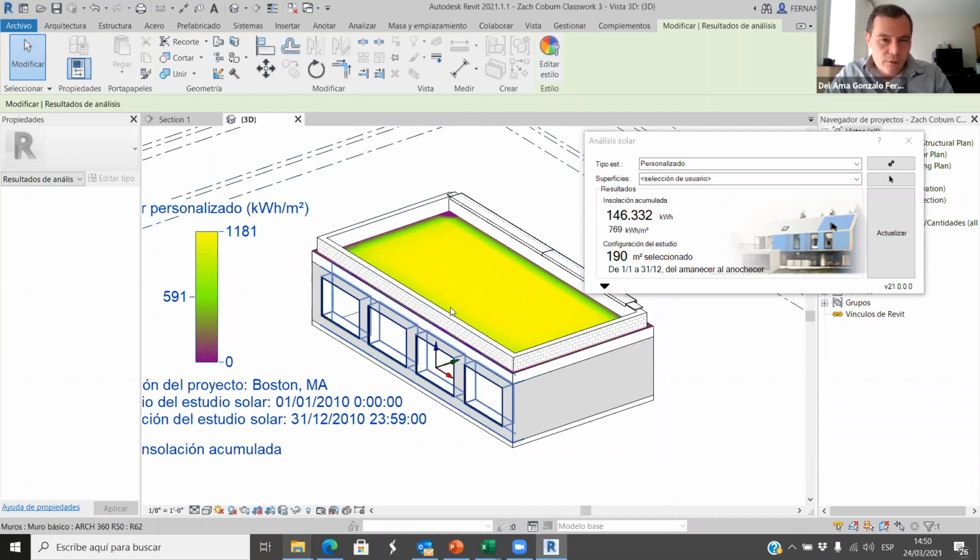And I think for the second part of the course, we can all work with this option, which is quite useful. But again, can we rely on Revit for this solar analysis? We need two different sources, and this is what we are going to do. We did this with the thermal loads. We use the Excel file, and we use the Revit loads report. And then by comparing these two options, we can understand, okay, we are doing well, or there's something wrong in one of the models. We will do the same thing with this option for the solar analysis.